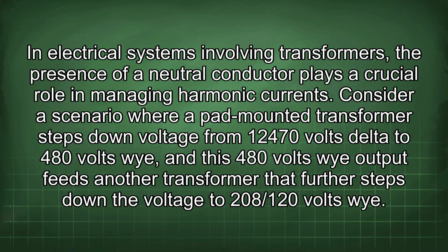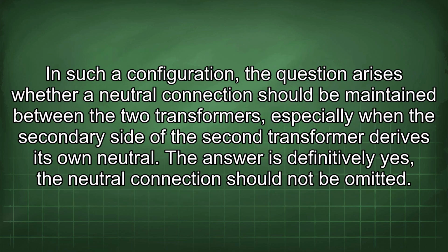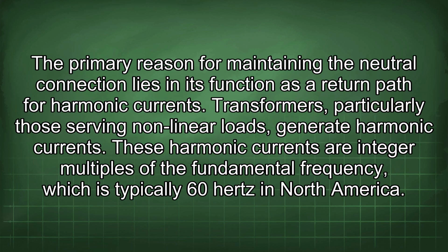208/120 volts Y. In such a configuration, the question arises whether a neutral connection should be maintained between the two transformers, especially when the secondary side of the second transformer derives its own neutral. The answer is definitively yes, the neutral connection should not be omitted. The primary reason for maintaining the neutral connection lies in its function as a return path for harmonic currents.